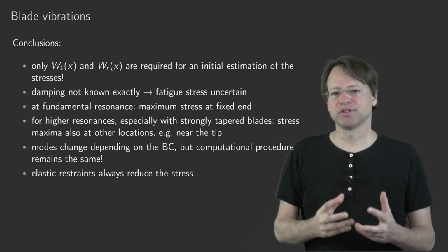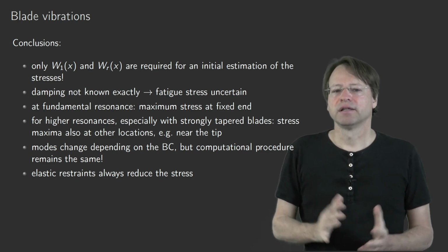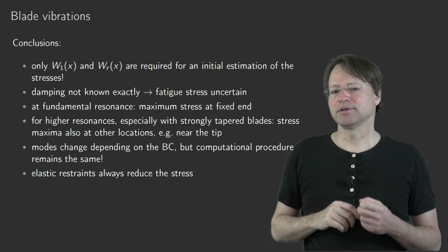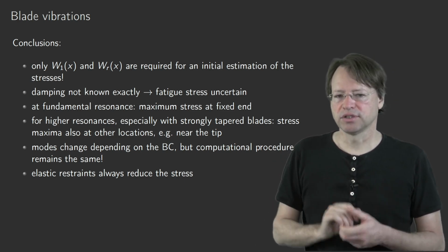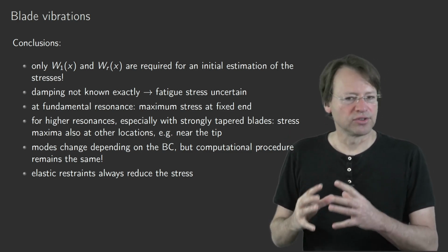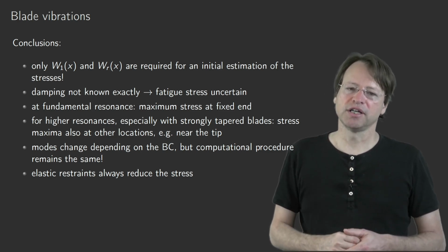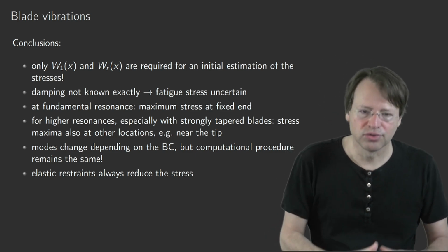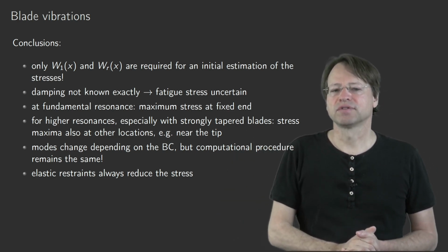So you have a problem specific approximation. If it happens that the homogeneous problem is too difficult to solve because of some nonlinearities or something else, you could try to reduce it to a simpler system. Of course, that must be realistic, that is solvable, and try to use these approximations of the mode shapes, or approximate first the mode shapes, the homogeneous solution, on that basis, and then use these approximations again in the Galerkin scheme for the forced vibrations.